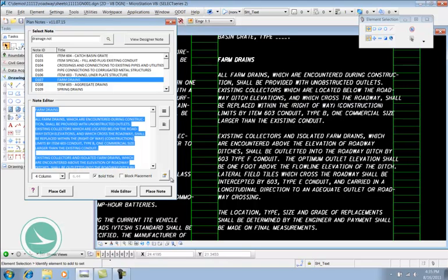The option button here for settings brings up a settings dialog that I'll just move over here to the center. There's a maximum stretch value and a maximum shrink value. That's set by default to 1.06% or 0.94%. So if it needs to stretch it, the most it'll stretch is 1.06%. If it needs to shrink it, it's going to shrink it 0.94.